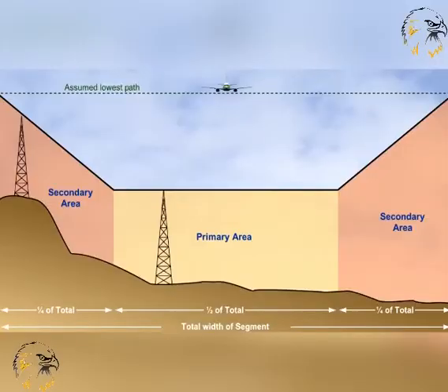Here is a vertical cross-section. You can see that, in the primary areas of the footprint, the full obstruction clearance must be guaranteed. However, MOC reduces to 0 as we move away from the primary areas through the secondary areas. If there is a particularly troublesome obstacle, then of course the departure track can be adjusted until the obstacle is overflown by a secondary area at a height that clears it sufficiently. This ends our discussion on minimum obstacle clearance during departure procedures.